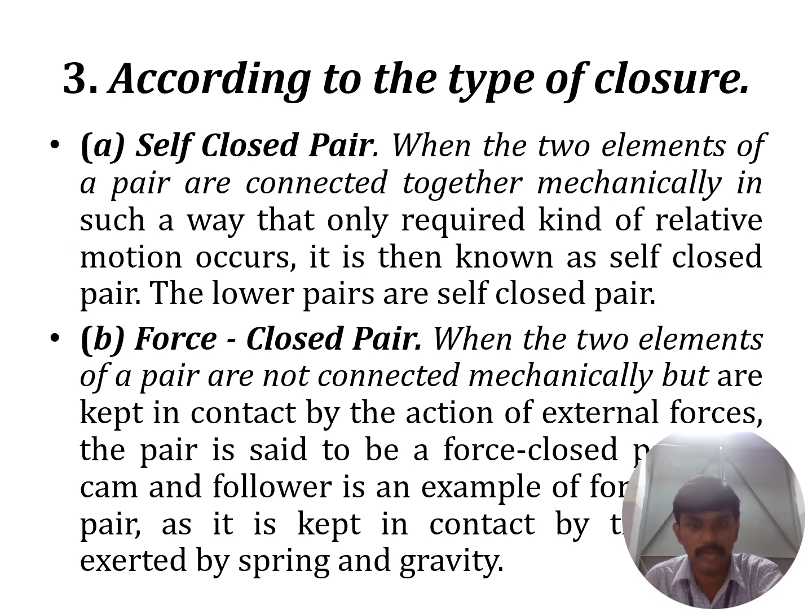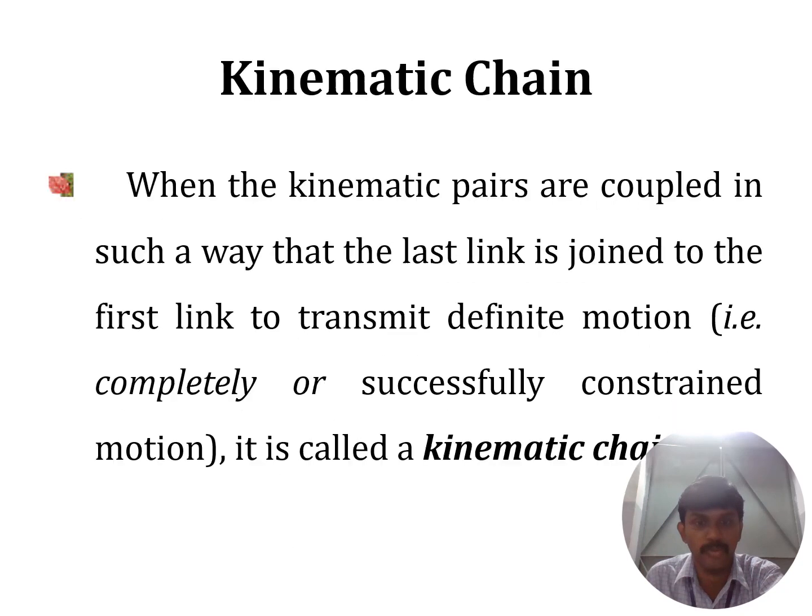In force-closed pairs, the elements are not connected mechanically, but contact is maintained by applying some external force. So the pair is said to be force closed, as with the cam and follower. The follower is fixed with a spring, meaning the follower is held by an applied external spring force. Due to the spring force, the follower contacts the cam. So it is known as a force-closed pair.